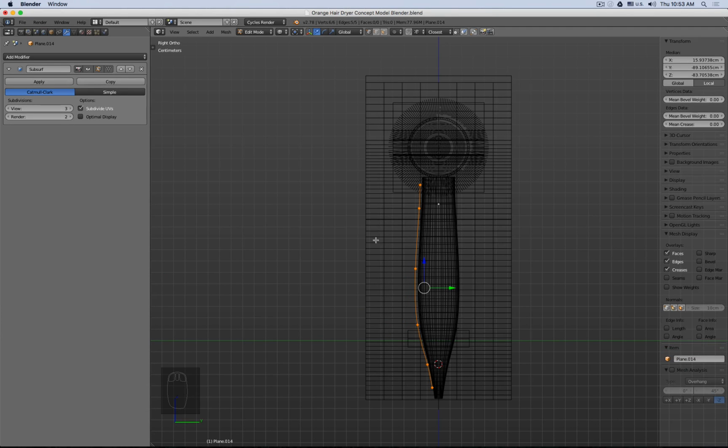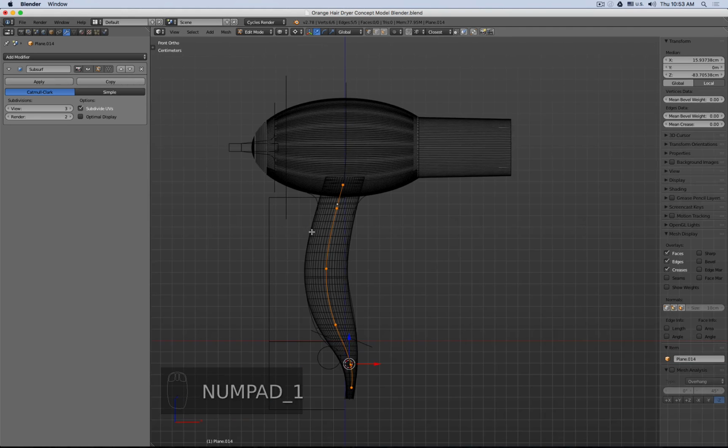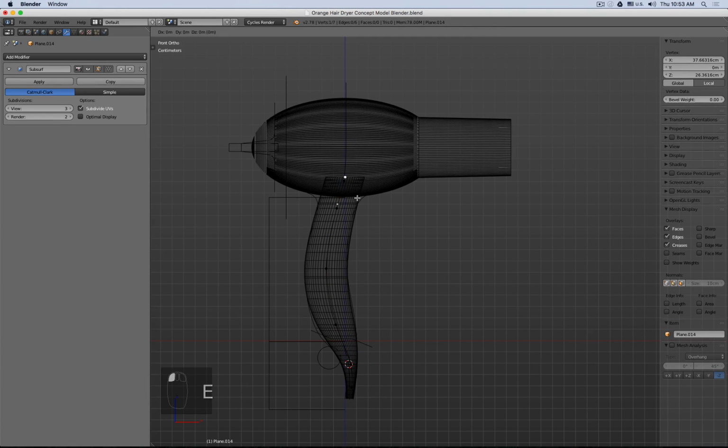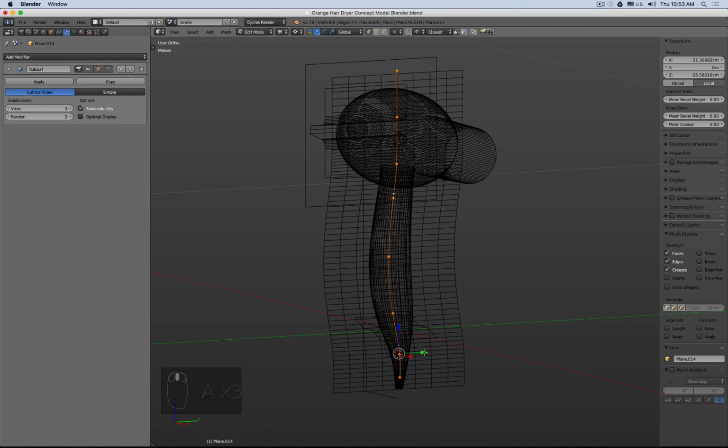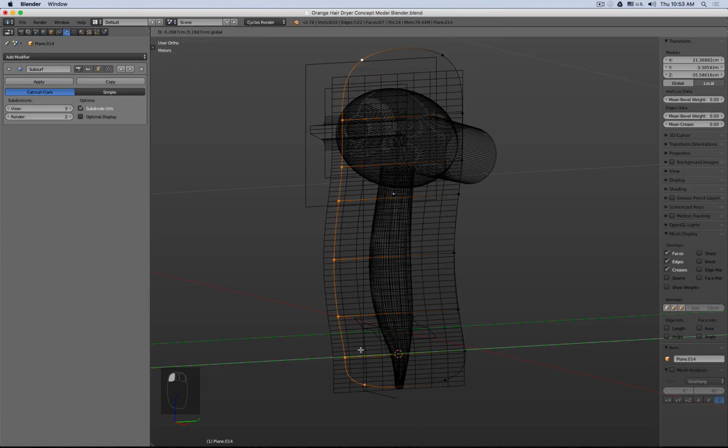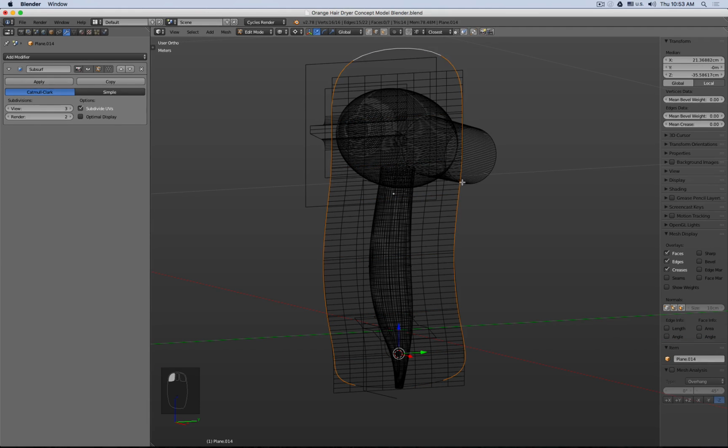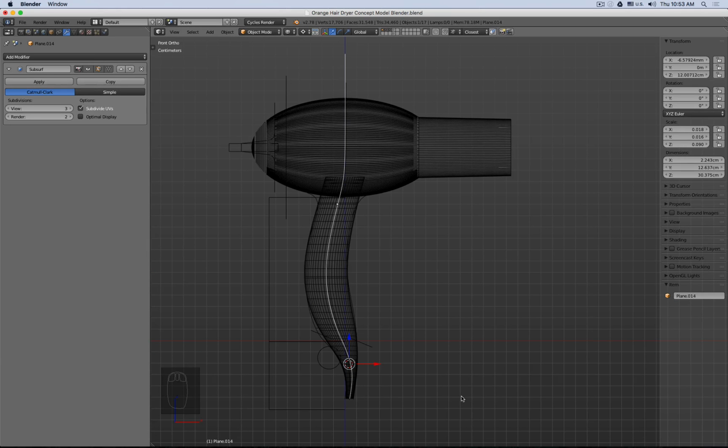mode, make sure your 3D cursor is at the center of your world, switch to 3D cursor, S Y 0, there we are, and then here E and Z, and there we are, A A, E, and let's extrude this one out, select this now, move to the left, and we snap also to the boundary, let's straighten it, and there we are.